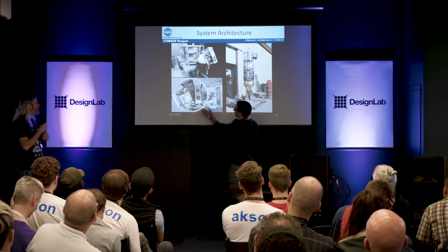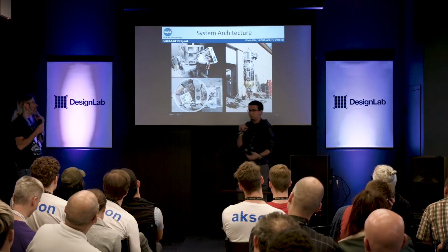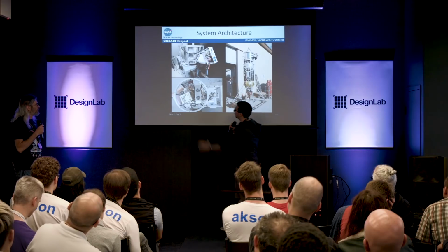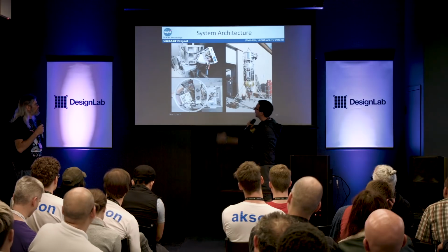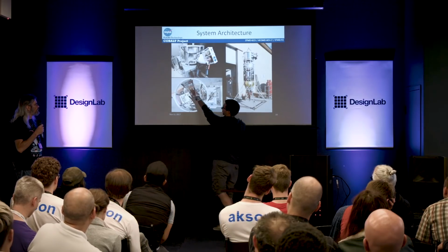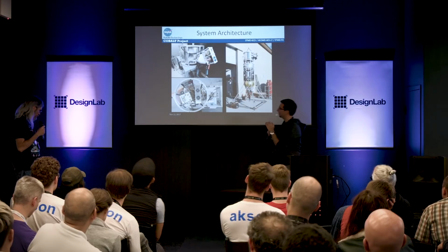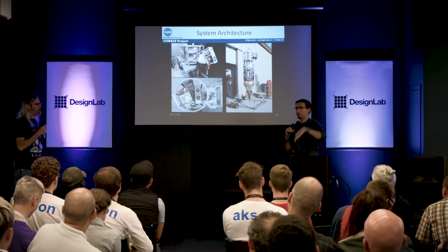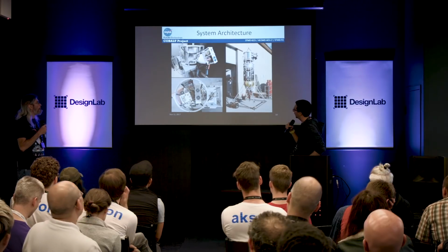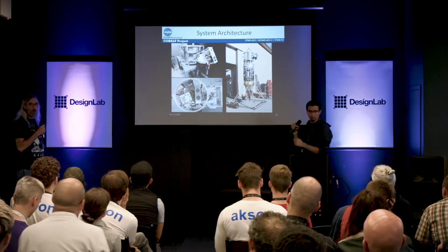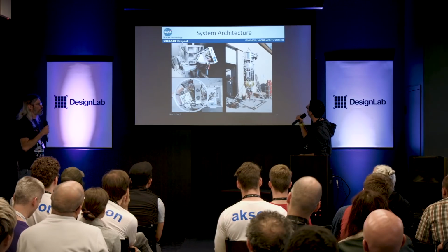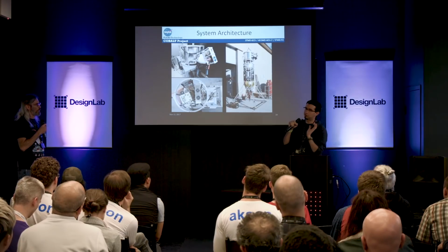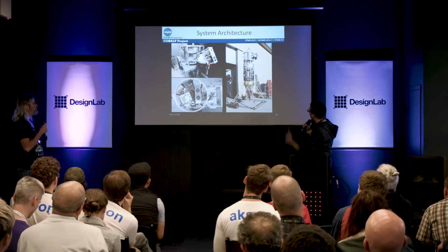Put together, this silver piece here is the compute element. We built a custom computer chassis, essentially. The white box here is the NDL electronics, and then you have the power condo. It's really hard to see. You see a bunch of terminal blocks at top, but it's made up of a bunch of decks that have various battery monitoring systems and batteries and stuff like that. And then an EMI shield surrounds it so we don't interfere with the vehicle and the vehicle doesn't interfere with us. So we bolted on top of their rocket.